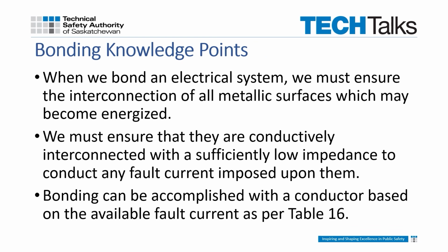Here are some key points about bonding. Bonding must ensure all metallic surfaces, which may become energized, are interconnected with a low enough impedance path to be able to conduct any possible fault current they may be exposed to. Because of the requirement to carry the fault current available in the system, the bond must be sized to Table 16 of the Canadian Electrical Code.